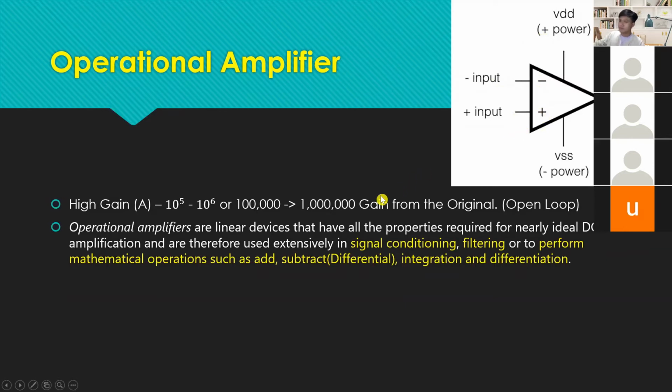Okay? So operational amplifiers are linear devices that have all the properties required for nearly ideal DC operational amplification and are therefore used extensively in signal conditioning, filtering, or to perform mathematical operations such as adding, which we now call a summing amplifier, or subtracting, the differential amplifier, or even integration or differentiation.